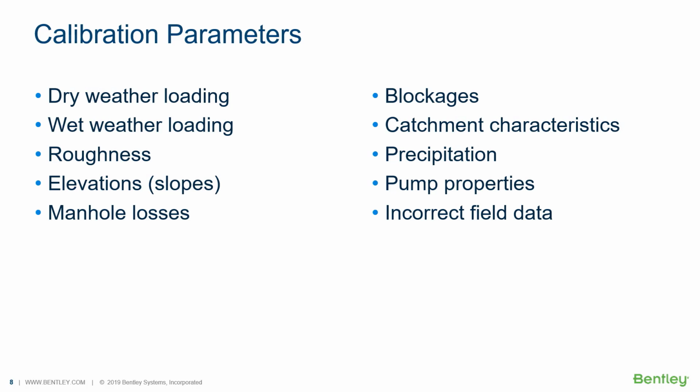If you have a pump system, you could have problems with the pump and with the pump properties that you have to enter, or your field data could just be wrong. People have been trying to calibrate models to match incorrect field data for years, and it's a frustrating thing when you get stuck in that situation.